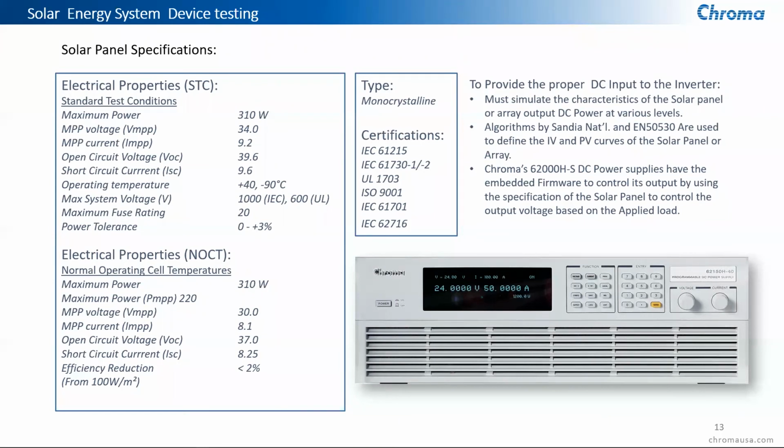And you'll notice that when you look at the specs on an inverter, you'll find things like open circuit voltage, short circuit current, operating temperatures, and various power levels based on maximum radiation levels. And it also gives you things such as efficiency and also some various types of protection tests that are also good.